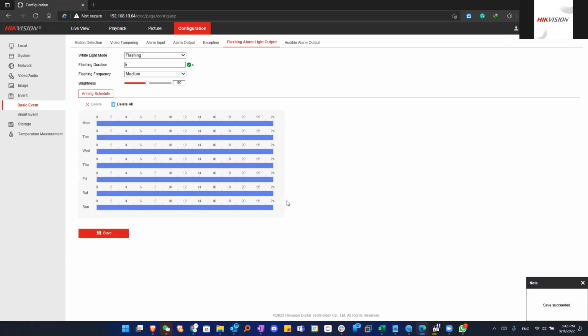In other alarm cases, we can give some exceptions, especially if it is a shop and you are doing some sort of motion detection. Sometimes you can disable it during shop opening hours and enable the motion detection only when the shop is closed. But for fire, you cannot have any exception. You have to monitor it 24/7. So if you are using these features, we recommend enabling the flashing alarm and audible alarm if it is available in the model that you select. Then make sure that the schedule is set for 24/7. Then you can ensure that it is going to work 24/7.